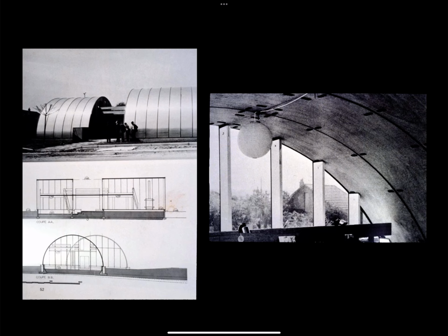But in fact, the skin of the building here is also the structure, and there is no other supporting framework, only the composite panels. And so this then is a shell structure in which the entire surface is working structurally. The skin and the structure here are monolithic. They are one thing. So these composite panels are three materials bonded together.